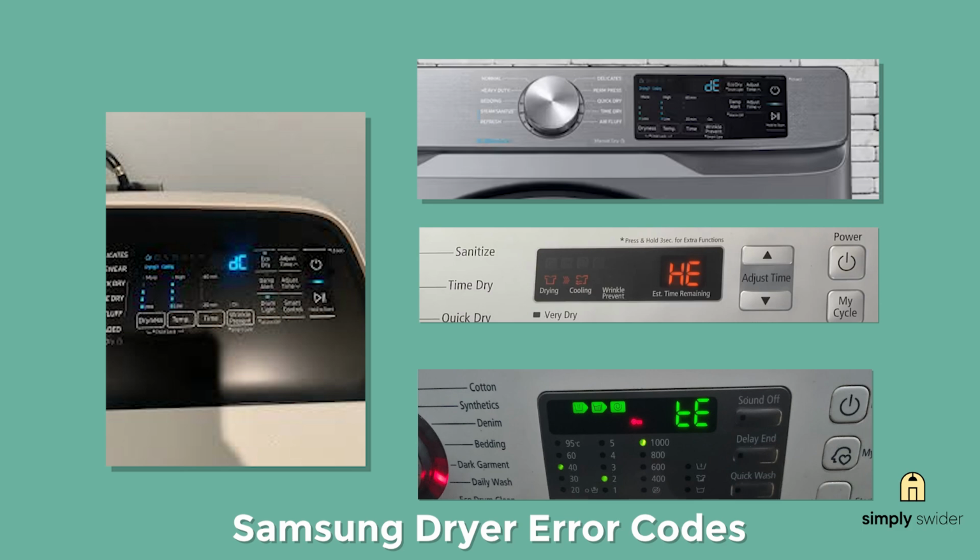If you're dealing with the more complex electronic errors like AC or 9C1, don't be a hero. Those usually mean control board problems that can get expensive fast. But for the heating, door and button issues, you can definitely handle these yourself and save some serious money.